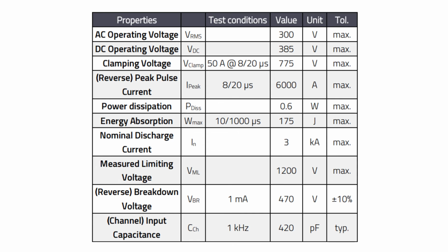According to the standard that we just talked about, the voltage of the test pulse for surge between a conductor and a return conductor is 2 kilovolts, and the source impedance is 2 ohms for low voltage network connections between live conductor and neutral conductor. The breakdown voltage, seen as VVAR or VBR, can be found in the varistor datasheet.